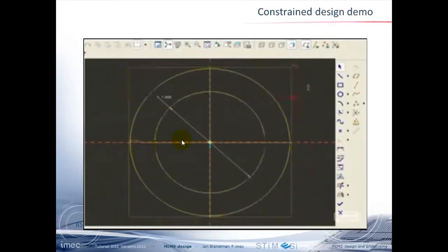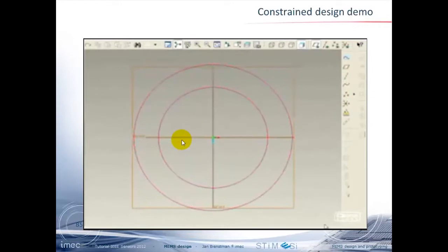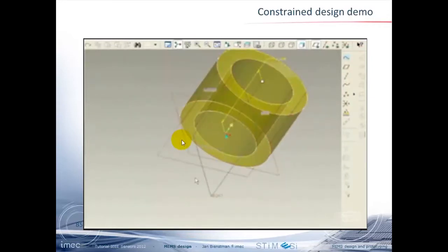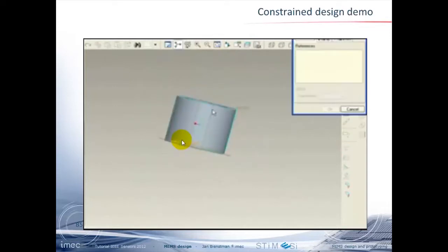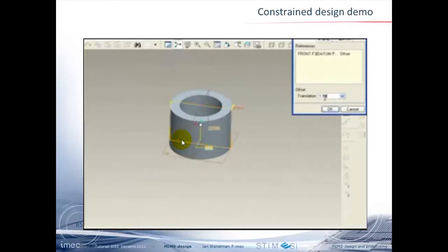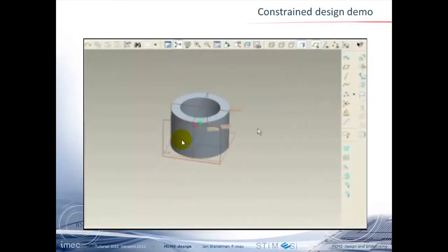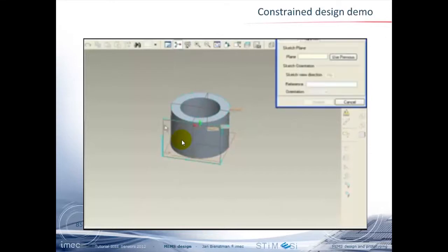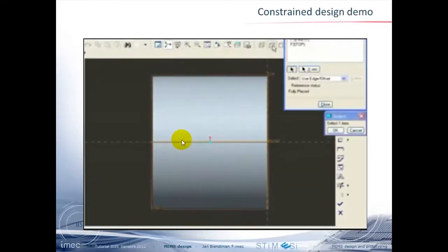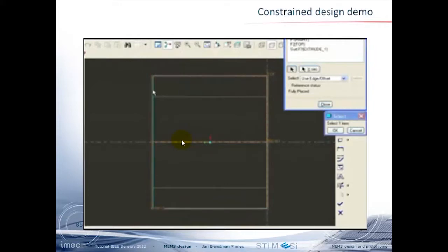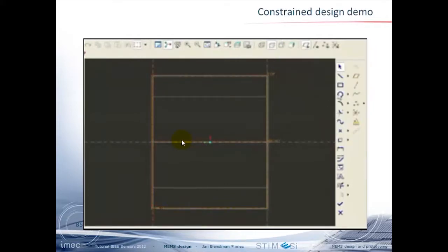So drawing circles, but then afterwards you put the dimension, selecting edges so that you tell the software that it's depending or ending on that certain face. You can do the same thing in a normal 3D CAD program, like AutoCAD, but then it's fixed in shape, it's not yet parameterized.